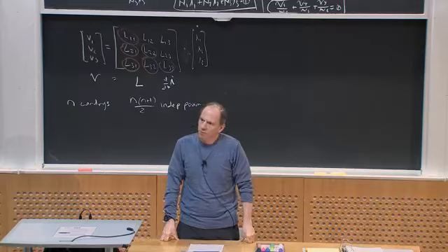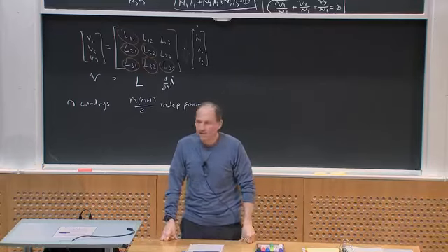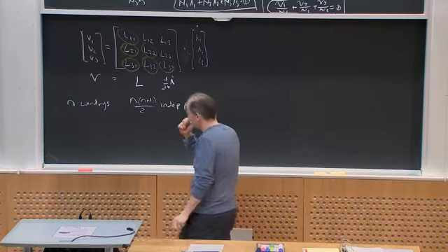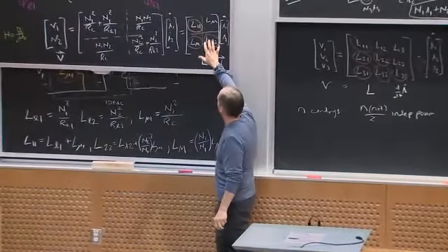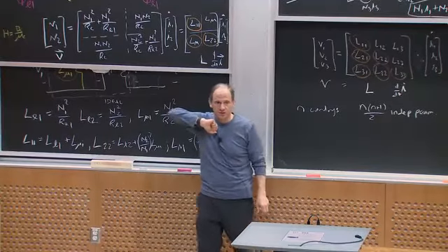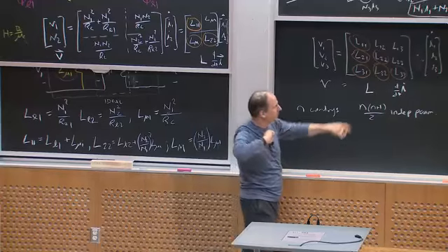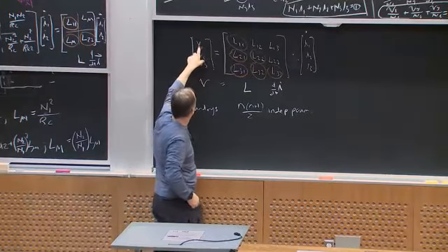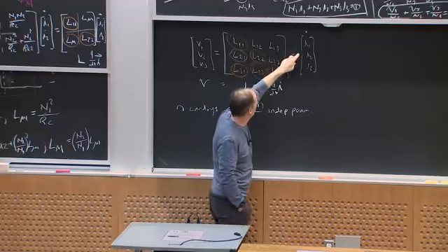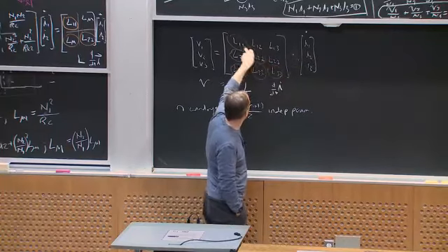So now what might I want? I might want the equivalent. I've already said I have an inductance matrix, and if I come up to my device and measure V1 and I1 with all the other currents open circuit, I can get L11.